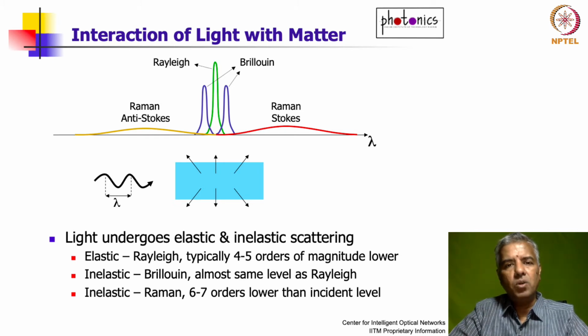Okay, so let's first look at Rayleigh scattering, and let's see how to make an instrument which can characterize the loss of the fiber. Let's say you have a long length of fiber with multiple bends and connectors and so on. How do you actually get information about that fiber by launching light into the fiber? That's through an instrument that's called an optical time domain reflectometer, and I'll talk about that in a minute.